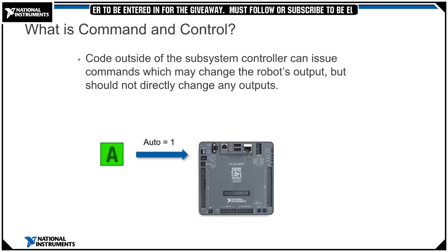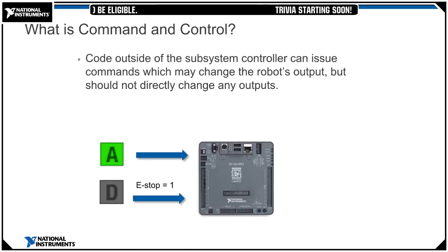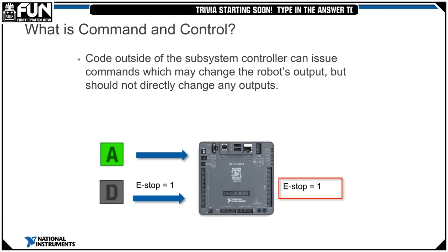Robot game code pretty much consists of autonomous and teleop, and typically needs to update set points and react to the states of different mechanisms on your robot. For autonomous, it's really common to define the robot's operation as a sequence of operations, right? Drive over here, pick this up, carry this here, drop it off here, etc. These commands can be wired sequentially with additional logic to quickly build complex routines, such as deciding, oh, I want to go to the left side of the switch or the right side of the switch. I can make game relevant comments now. This is really exciting. But things like that can help you build these complex routines.